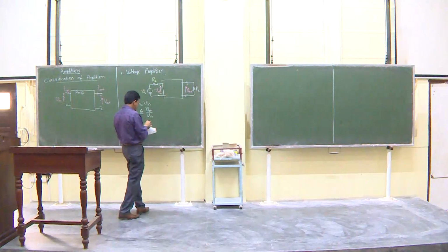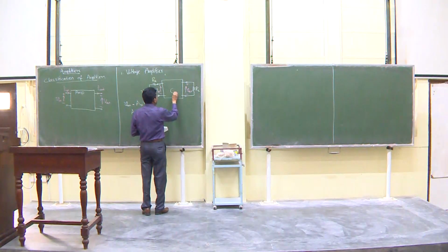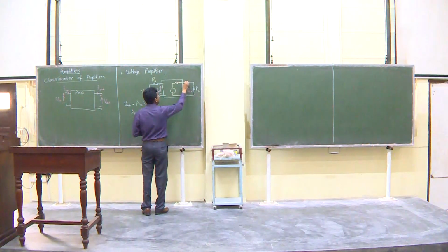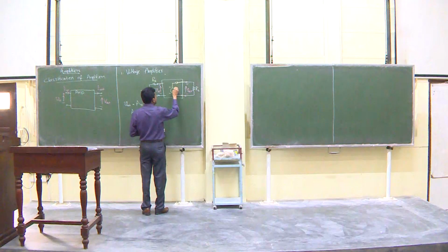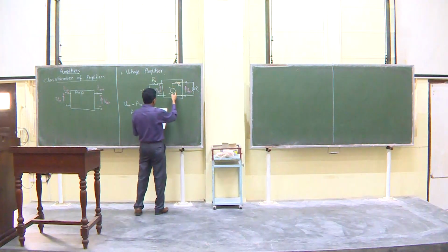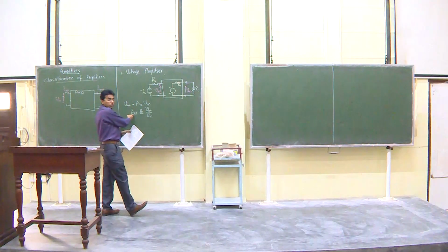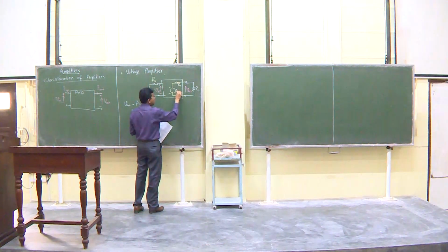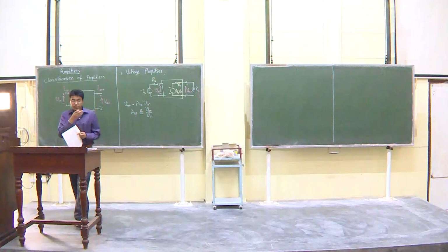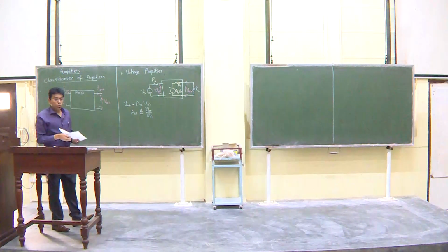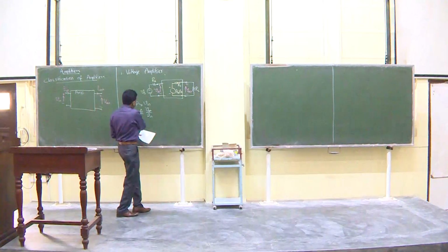So inside this is a voltage source in series with an output impedance, let's call it R out. The voltage source has to be the voltage gain that I want, that is AV times the voltage V in. That's my Thevenin's output voltage, which is related by this definition.